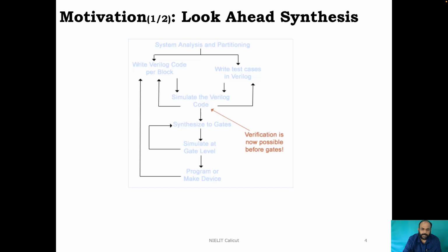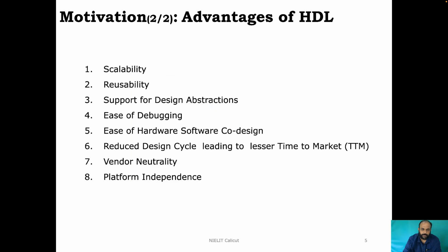Also, we can use the same Verilog, or an extended version of it called SystemVerilog, for writing verification as exhaustively as possible, so that every single corner case, or every single case in which the hardware can fail, can be explored before we go for synthesis. So the synthesis will become very smooth if you are using a hardware description language.